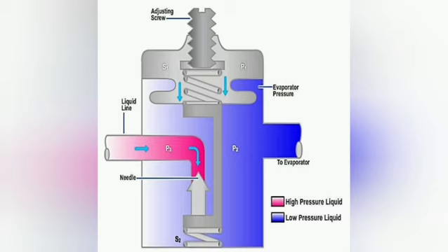After leaving the condenser, the high pressure liquid passes through the expansion valve. The expansion valve suddenly reduces the pressure of the refrigerant. Because of this pressure drop, the refrigerant temperature also decreases. A cold, low pressure liquid-vapor mixture then enters the evaporator and the cycle starts again.